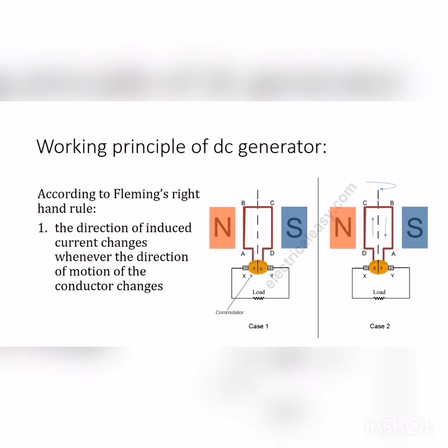Let's consider an armature rotating clockwise and a conductor on the left is moving upwards. When the armature completes a half rotation, the direction of motion of that particular conductor will be reversed to downwards. Hence, the direction of current in every armature conductor will be alternating.